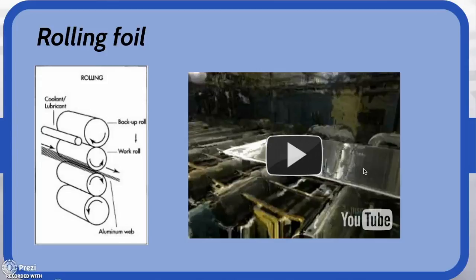As the sheets of aluminum pass through the rolls, they are squeezed thinner and extruded through the gap between the rolls. The work rolls are paired with heavier rolls called backup rolls, which apply pressure to help maintain the stability of the work rolls. This helps to hold the product dimensions within tolerances. The work and backup rolls rotate in opposite directions, and lubricants are added to facilitate